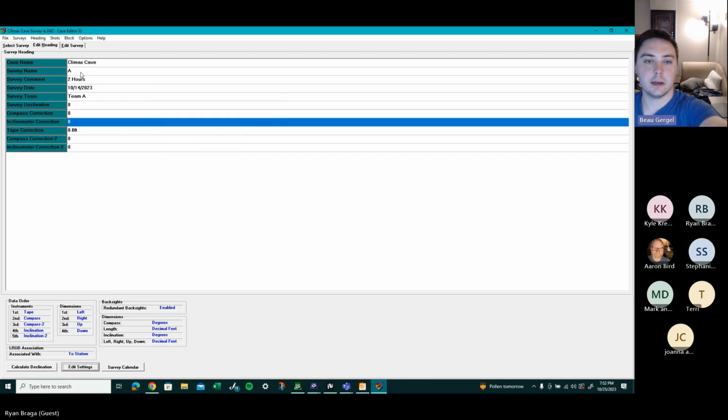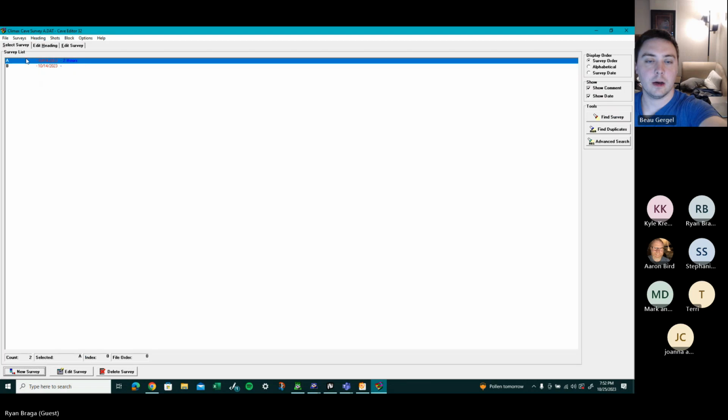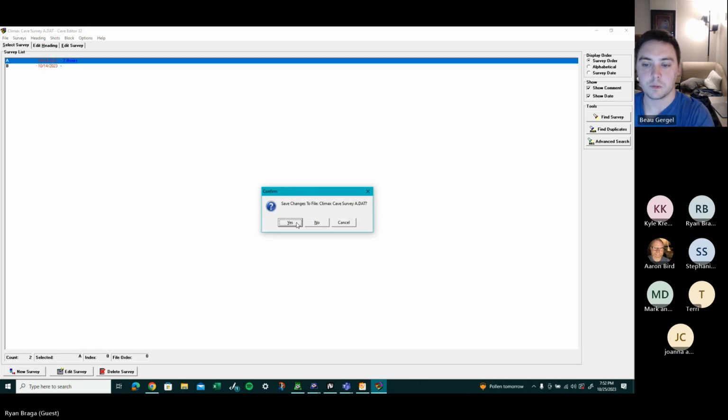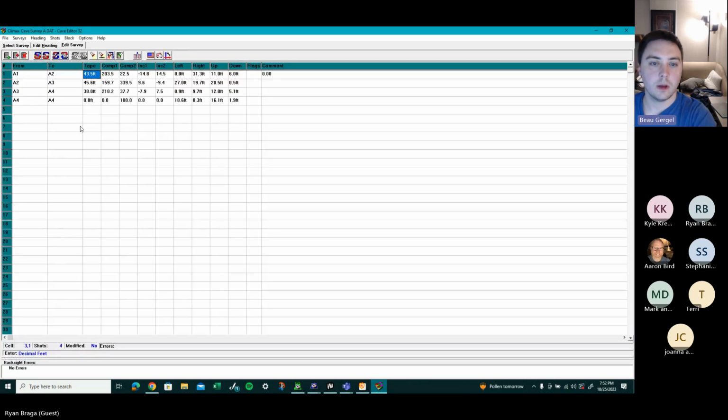And then go back to the survey, the edit survey, sorry. All right, your column says from and to. So when you put the LRUDs in, you're putting the LRUDs from the from one. So A1 LRUDs went in left, right, up, down because you had from marked. If you had 2 marked, it would be the A2 LRUDs that you would have actually been entering there, if that makes sense. So that's all that setting is.